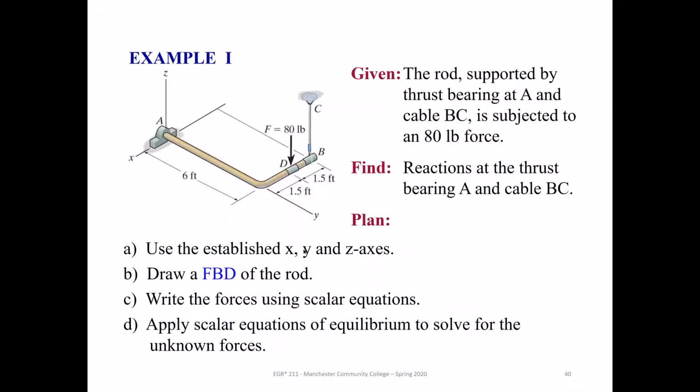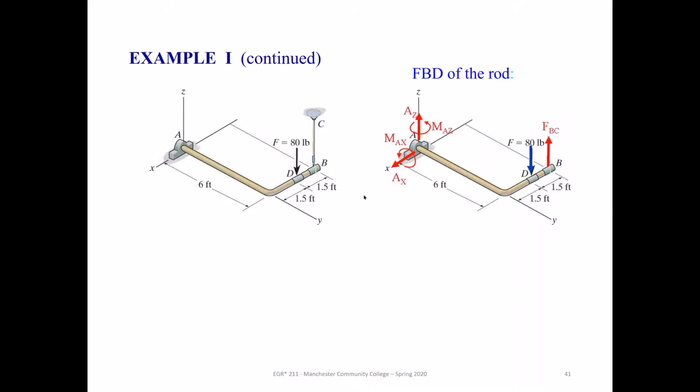So first part, X, Y, and Z, we already have those. And now what we're going to do is put in the reactions. So we have a reactive force in this direction, and of course, this bar can slide in and out. So there's no reaction along this axis, which is our y-axis. In a problem like this, you might need to set up these axes in a way that works out conveniently, like this problem was set where this bar was right along the y-axis. So you can see that sliding in and out would mean that you have no reaction in that direction.